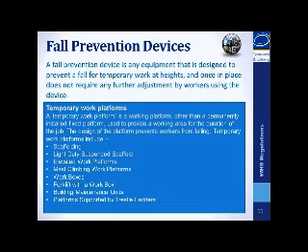A temporary work platform is a working platform other than a permanently installed fixed platform used to provide a working area for the duration of a job. The design of the platform prevents workers from falling. Temporary work platforms include scaffolding, light-duty suspended scaffold, elevated work platforms, mast climbing work platforms, work boxes, forklifts with work boxes attached, building maintenance units, and platforms supported by trestle ladders.